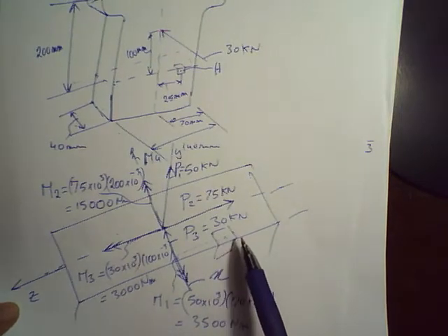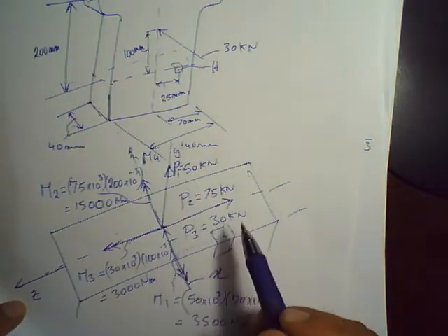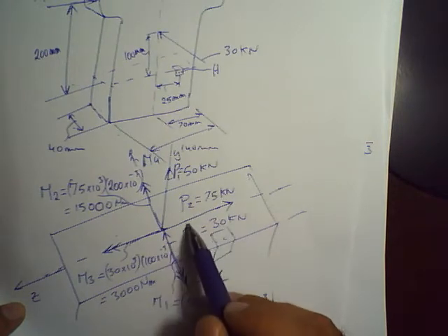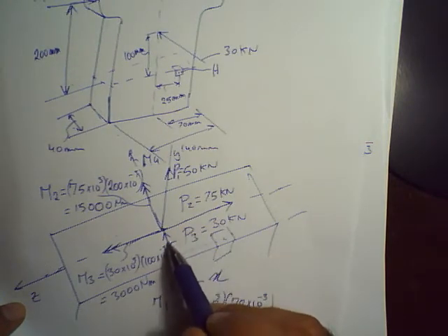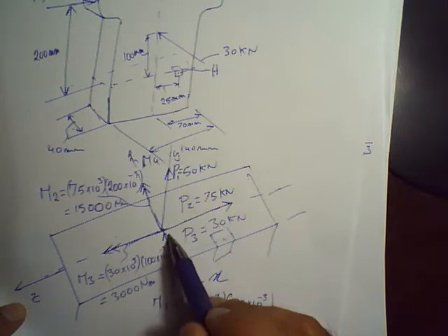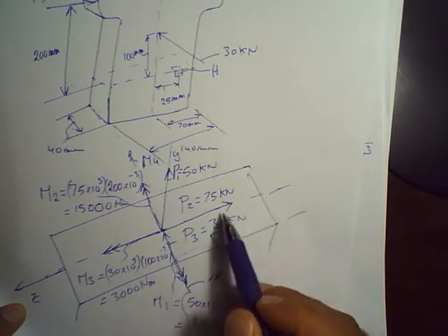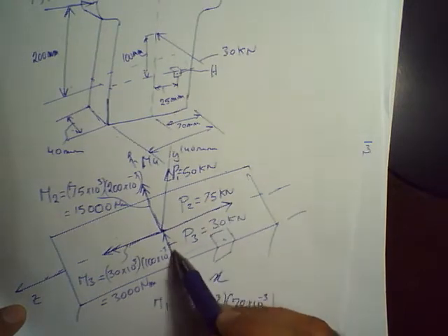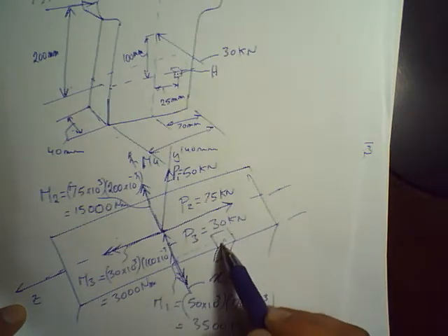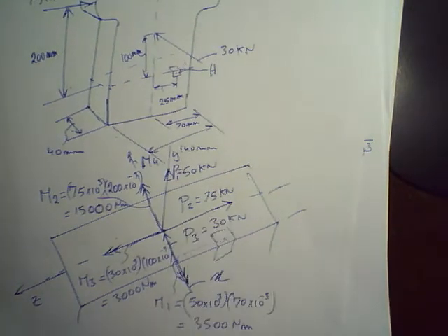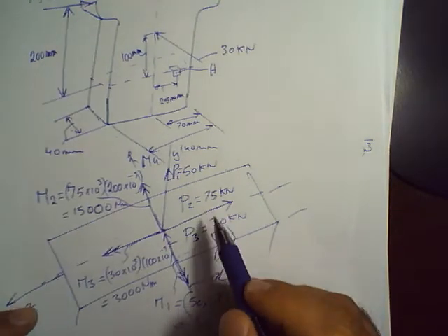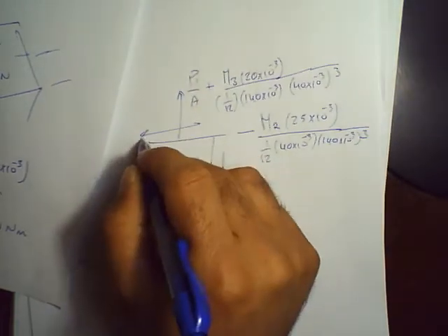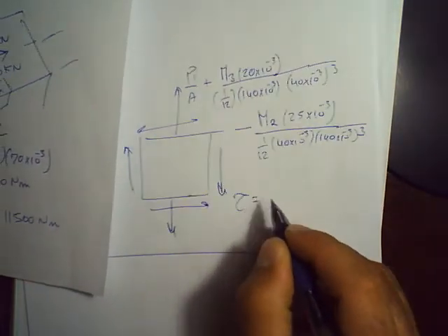And then how about the shear? If you have any shear, basically, that's going to be caused by which value? So we have P2 and then we have P3, right? If you consider the stresses caused by P3, they are maximum at the neutral axis, right? And then it would be 0 here and then 0 there. So P3 does not create any shear stresses here. How about P2? P2 does, right? So we have shear over here. So the shear is going to be equal to what?